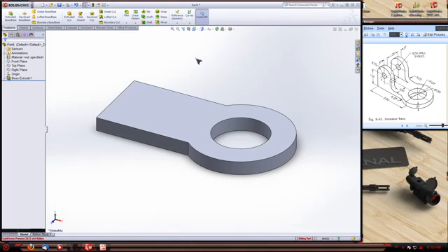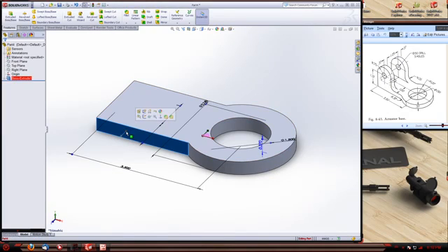in the least amount of steps, we could extrude these two arms here up as rectangles, or we could draw on this surface here and extrude it as a solid across this and then subtract the channel out of the middle of there.